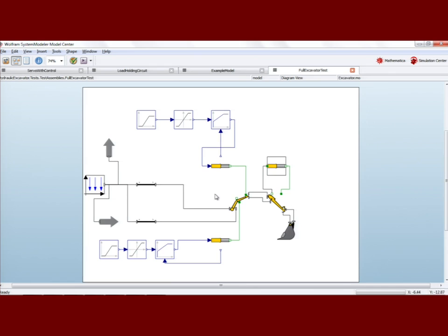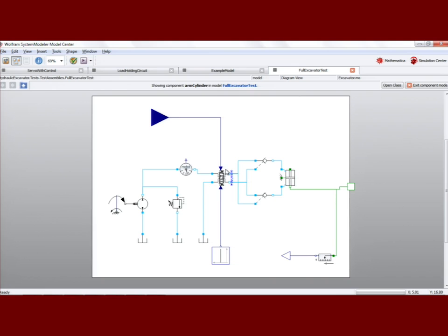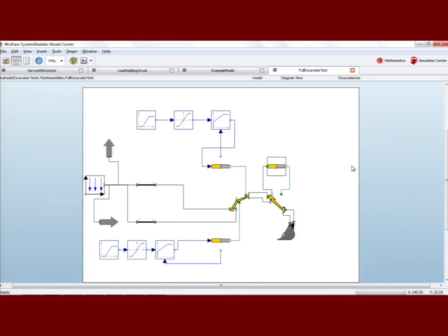And we can see now that we have these components, which were the mechanical components modeled before, and we have added hydraulic systems to them. So in each of these, we can click in and see that it's actually a similar system to the small servo mechanism we had. There are some different things, like these check valves, which have an assistant pressure in order to give a smoother movement for the hydraulic system or for the bucket. So the hydraulic system will typically be something like this. We connect several of them, and we get this excavator. So let's simulate that.